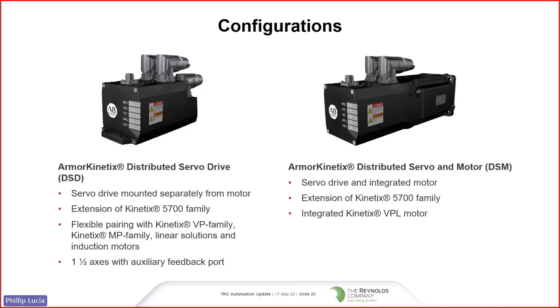Both of these versions use a daisy-chainable special single cable that transmits power, feedback, and data to drastically reduce enclosure sizes by moving the access modules out to the machine and slashing cable runs and install time, since you no longer have 2 cables going back to the panel for every single motor.